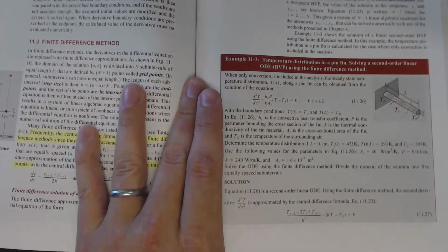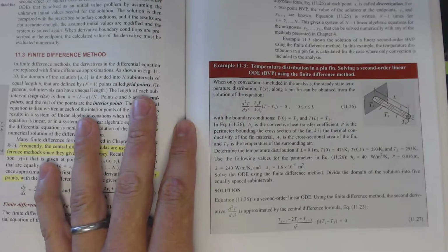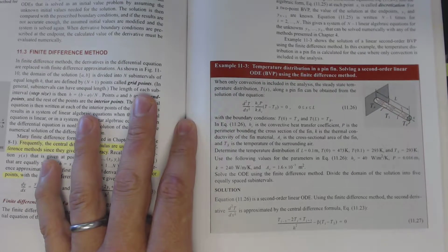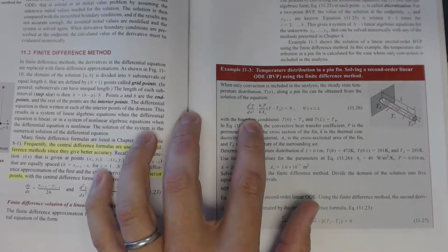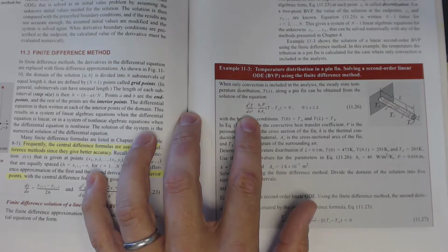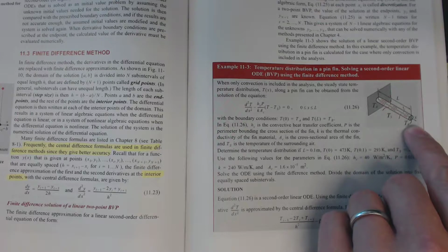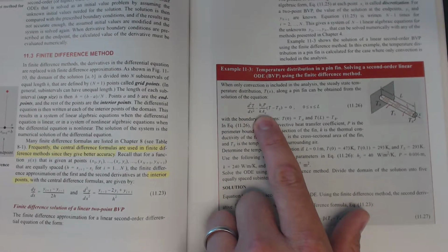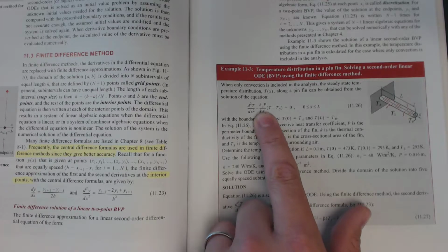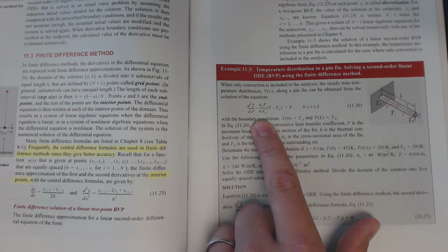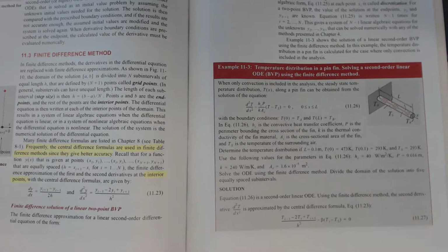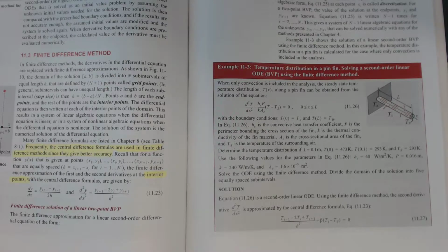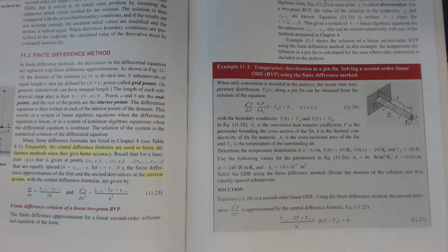Looking at a practical example that's quite easy to follow, and hopefully my comments will add some merit beyond simply what the book would tell you. The second derivative of temperature with respect to space on this small pin fin equals a collection of coefficients corresponding to the physics of the problem, where in this case h is a convection coefficient, p is the perimeter of the rod, k is a conduction coefficient, and Ac is the area of the fin. That's then multiplied by the temperature at that point minus the surface temperature. All equals 0. Valid in the region 0 to L, where L is the length of the rod.